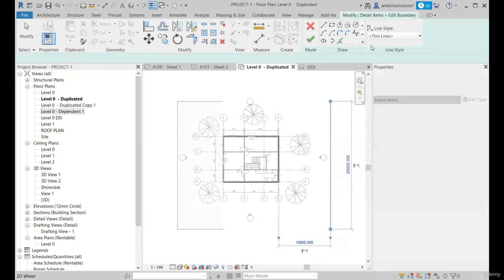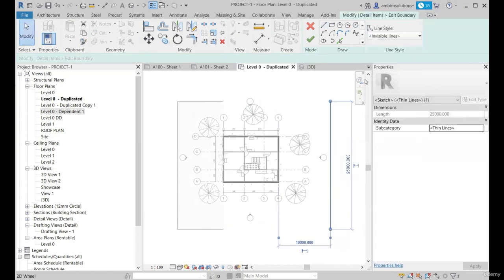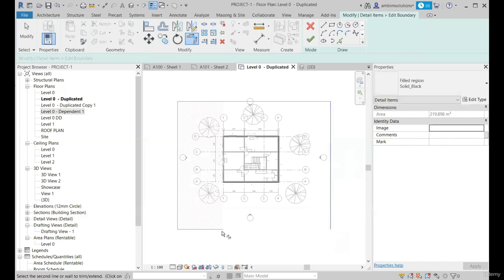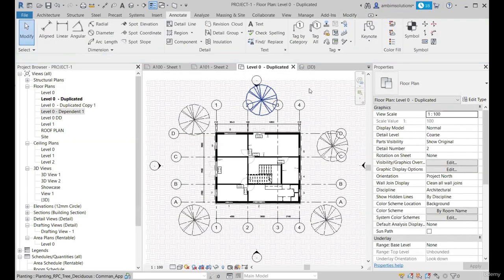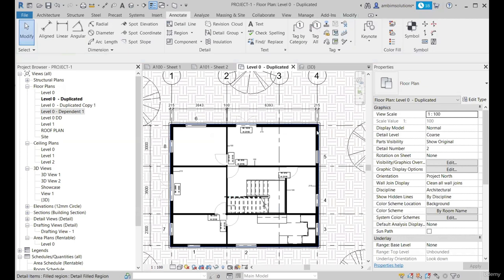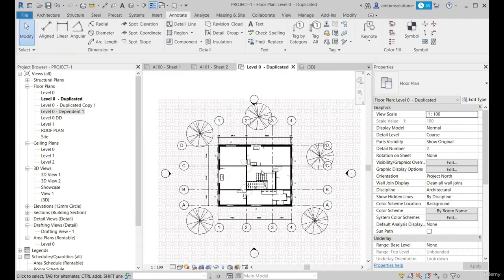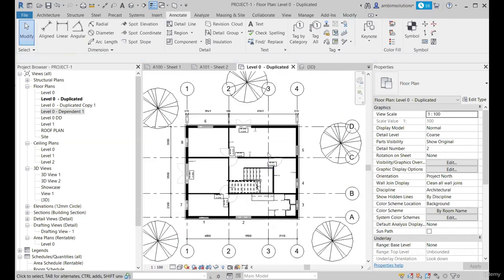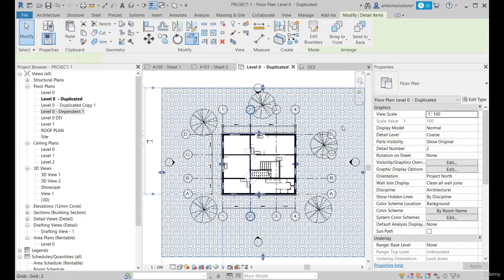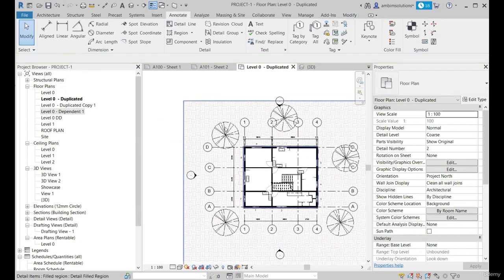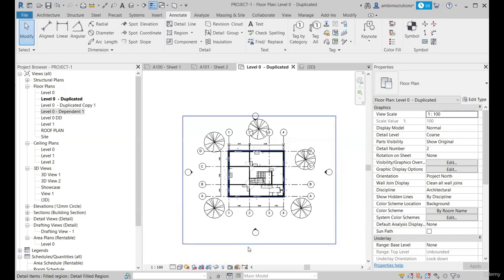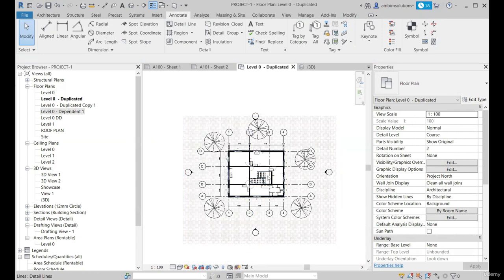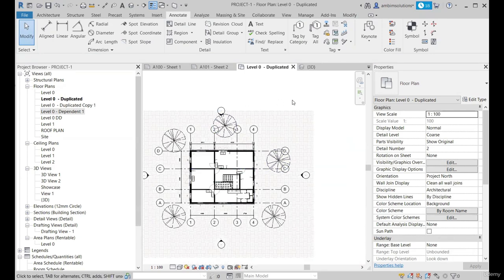And here we have, let's keep it invisible. Let's trim these lines, and hit OK. Now let's see. There is a ground on the exterior side and nothing is present on the interior side to make the view clear and clean. So in this way, you can create any region as per your preference. You can create any pattern. You can give any color to your filled region.